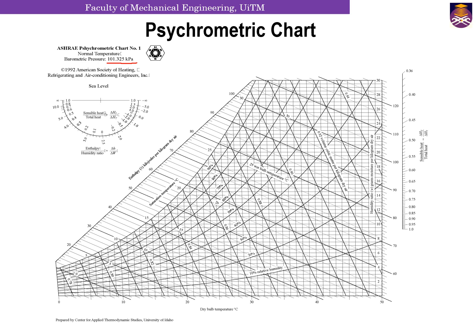As you can see from here, you have the psychrometric chart shown as what we've discussed earlier in a shoe form. On the y-axis here, you have all the values for humidity ratio. This humidity ratio, bear in mind, the unit is in grams moisture per kilogram dry air.